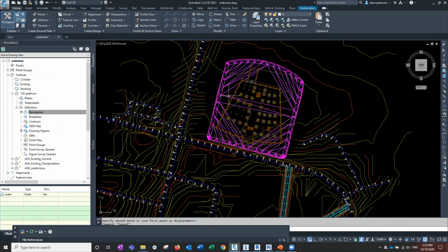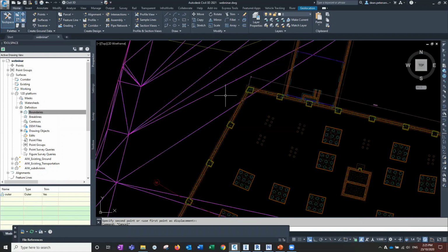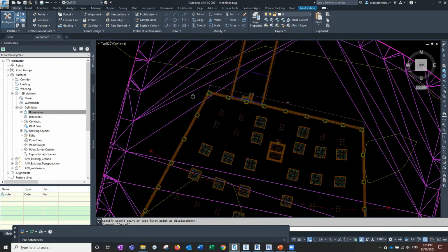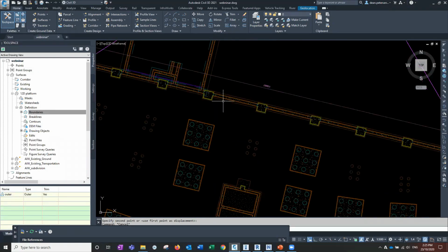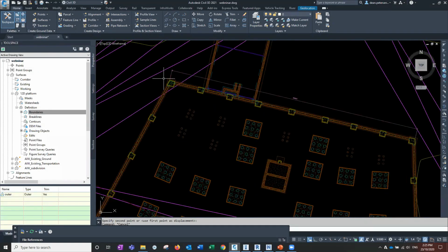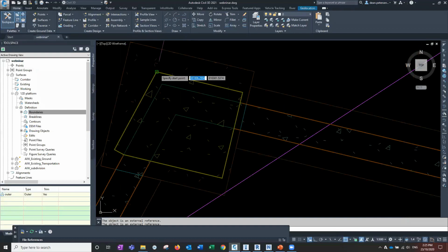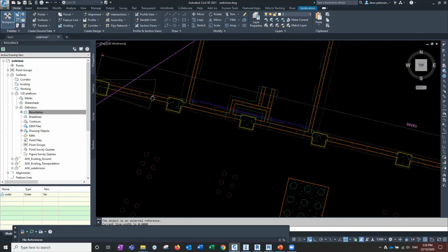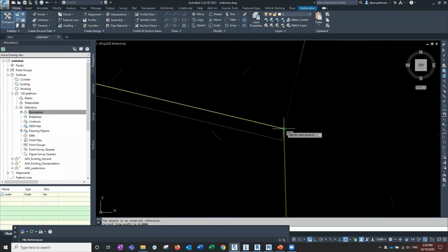All right, so I want to draw myself a little line that is exactly the same length as what's in Revit. So I'm going to snap to that polyline. So it's going to be from this corner there, and make sure you do get the corner. If you don't get the size quite right, it goes into the wrong place in space because it's a different distance from the origin.